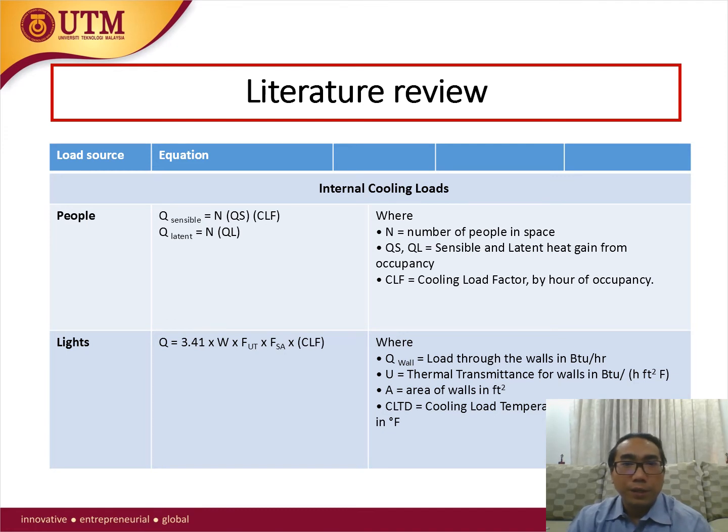The weighting factor equation determines the CLF factors. CLF equals Q cooling load divided by Q internal gains. Note that the latent heat gains are considered instantaneous.